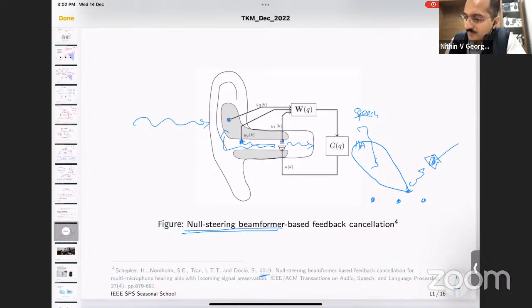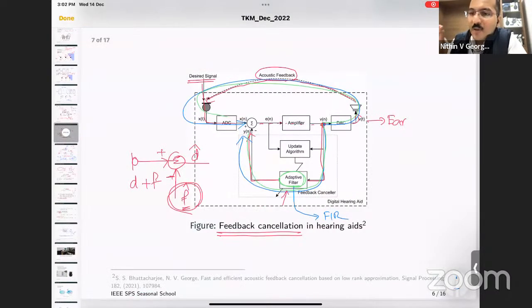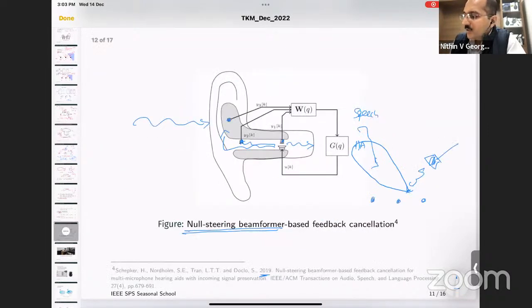So our original problem, which we saw over here, had 1 microphone, 1 loudspeaker, and we have the feedback problem. We try to do a signal processing solution to that. But if you read it properly, it will say there is a problem of bias which is going to come, so this solution is not a very good solution. Okay, because there is some finite correlation between the signal and the noise. But here, the same problem, I am now formulating as an array signal processing problem, where instead of 1 microphone, I am deliberately putting 2 other microphones, where I could do something called spatial filtering.